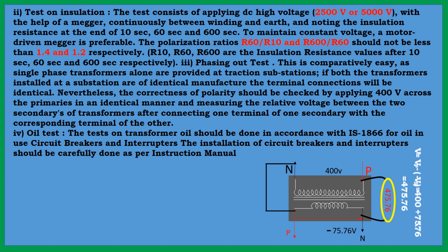Okay, and next is the polarity test of the power transformer. For the polarity test, you check each transformer individually, because in a traction substation there are two traction power transformers. One is for standby. In our power supply system, 100% standby is there. If one is incapable, under maintenance or under breakdown, at that time the second bay will work, because traction supply is an urgent power supply to run the traffic, the trains, so it cannot be interrupted. So 100% standby is there.